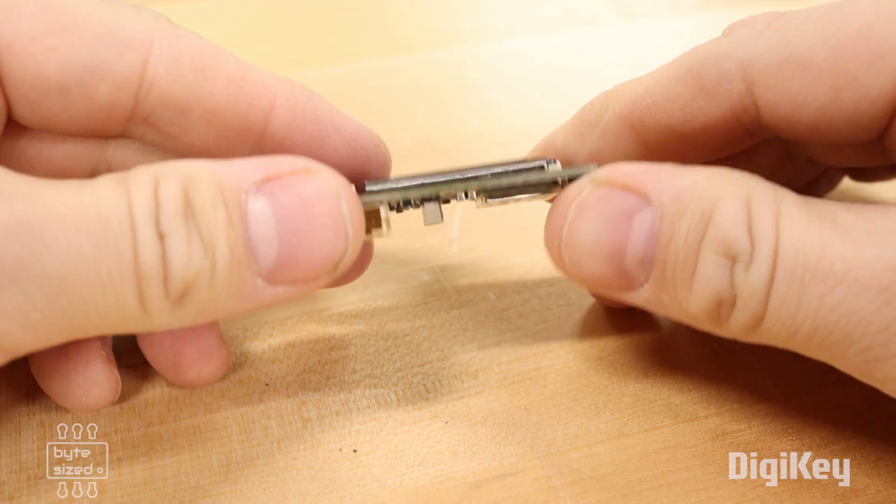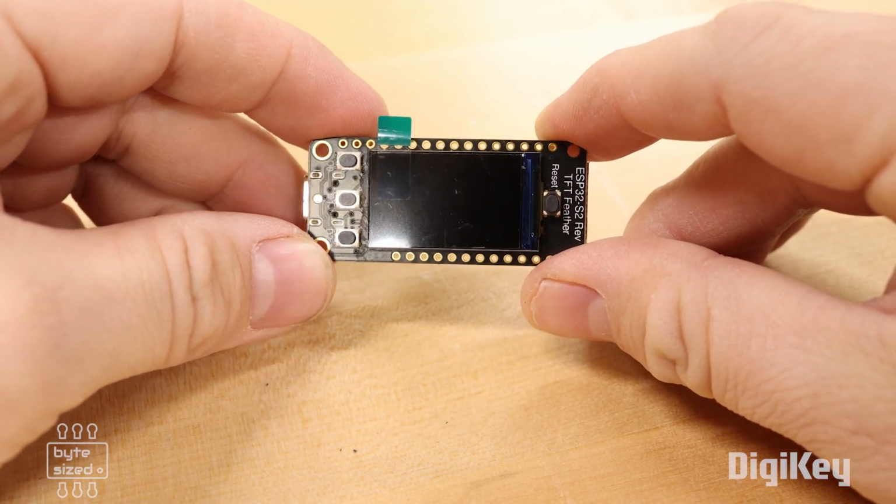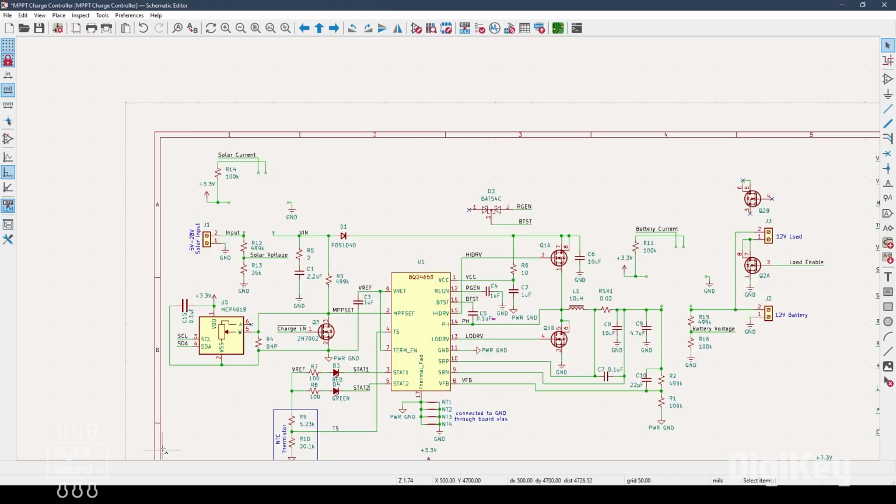The microcontroller that I chose to use for this project is the Adafruit ESP32 Reverse TFT. It's got a TFT display as well as 3 buttons, so I can write a nice little UI for it. I want to be able to measure and monitor the voltage as well as the current, so I'm going to use the ADC pins on the microcontroller to measure voltages, and then I'm going to throw on some current sensors on there that the microcontroller will use to read the current.